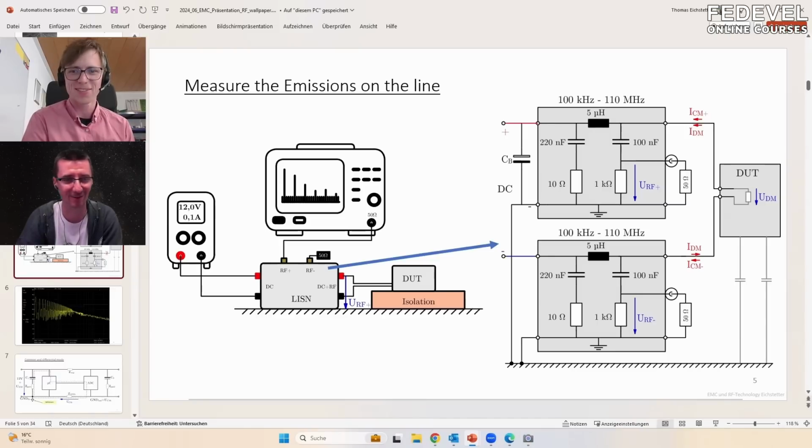Minus. Okay. Yes. I didn't want to say ground. Yeah. But actually, here with this one here, you can say this is the reference. Okay. And with reference, you can also use it as ground. You know, ground has two functions always. Which one? It is once the reference, and the other one is the equalization of the current. Okay. And because these two functions compete with each other, people always have a problem with ground and also to name them. Okay, let's go back to the picture.